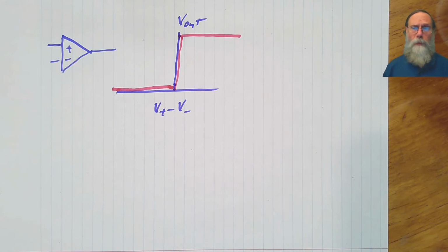That's different from what we did with the op-amps. The op-amps are designed with an internal low-pass filter so that when you put them into feedback circuits we don't get oscillation and other unstable behavior. The comparator does not have those internal limitations. It doesn't have the internal slew rate limitations or the internal low-pass filtering, so the comparator makes its transition as fast as possible given the technology.